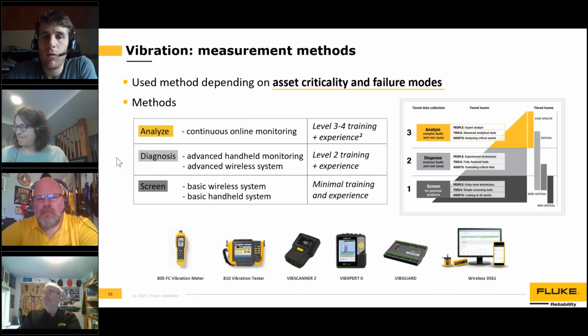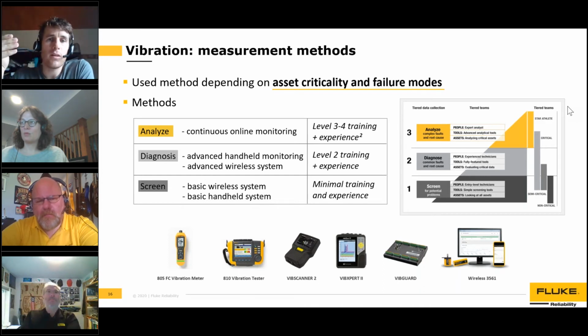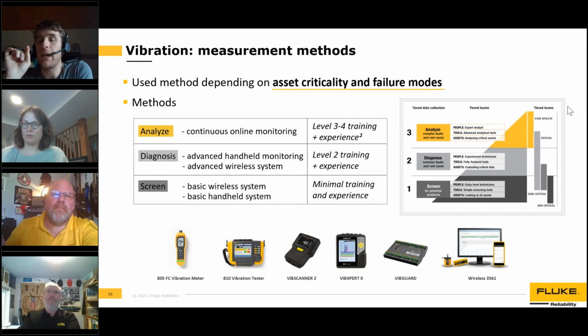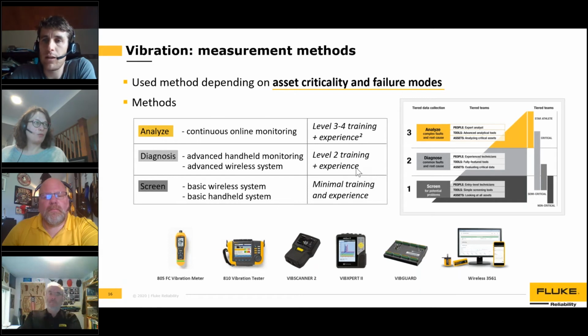And then maybe one thing I want to add on that previous question: when we talk about analytics, I explained the most basic form, but today we're also already using advanced online monitoring systems, with AI engines and other machine learning systems continuously looking at that data, and they can pinpoint failure modes right out of the data. Hey, ping, here's a flag. And it's not just a condition change. No, it's a flag saying this machine has an imbalance. This machine shows an early bearing damage. So we're already going that far with this AI and machine learning technology.